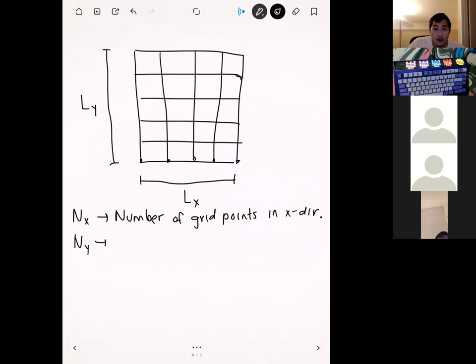The way that you obtain nx is that you simply go horizontally across and count how many nodes there are. In this case, we have 1, 2, 3, 4, 5. Since we have a rectangular domain, nx is going to be the same no matter what level you're at in the rectangle. So in this case, our nx is equal to 5.